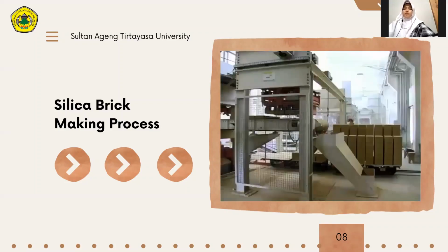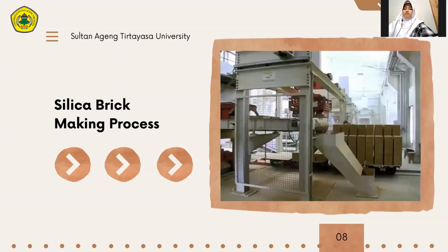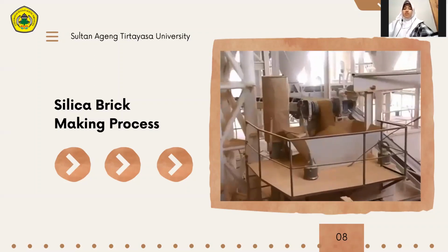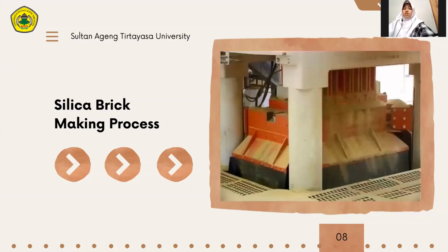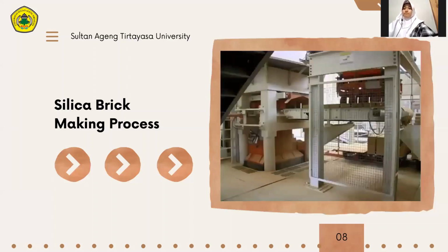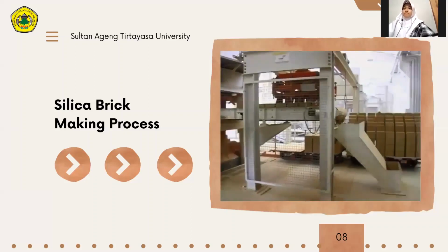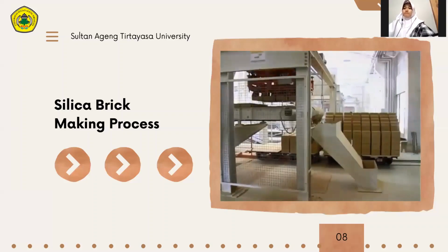Thus, about 10,000 bricks can be manufactured per hour with the max pressing power up to 750 tons. Pressing process has 3 major stages: loading the mass into the press mold, mass compression and stripping of the sand lime bricks. It is possible to manufacture bricks of different types and formats using special press molds.